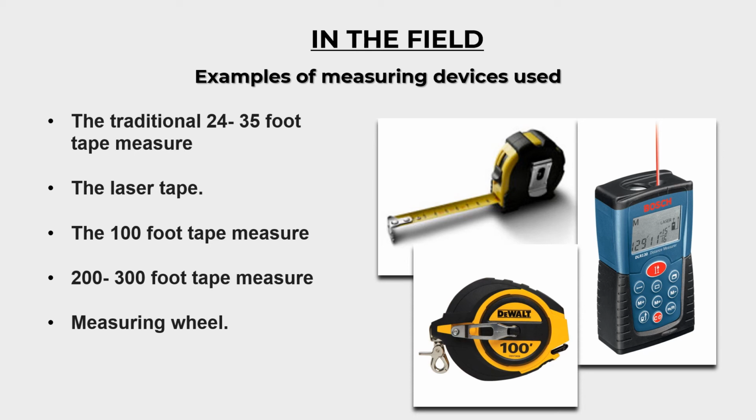And you could also use a measuring wheel. However, keep in mind a measuring wheel goes along the ground along the grade, so you're actually getting the length of the travel along the grade and not necessarily the actual length of the structure itself. So that's something to keep in mind.